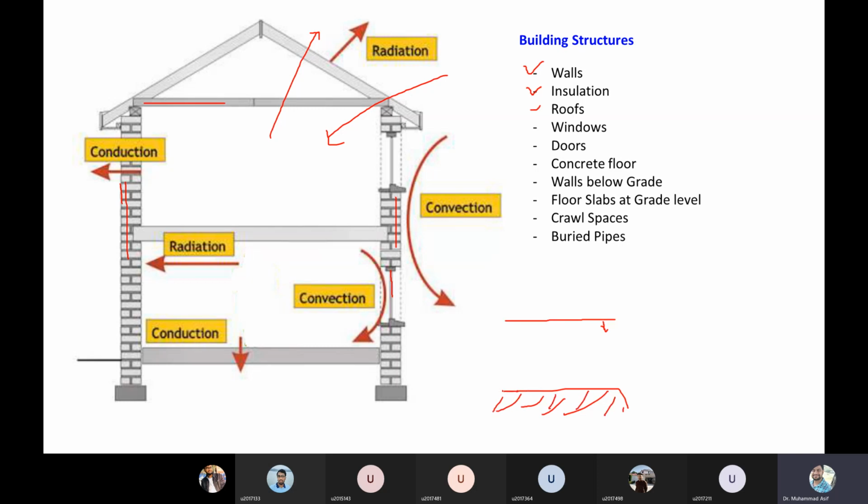And then on the soil we put concrete, right? We normally call it RCC, reinforced concrete. And then we put the grade, that's a layer of the grade. And then there is an unfinished concrete, and then we have the final flooring. In some cases they also mount some tiling as well. So when I say the floor may have many layers, it depends on the types of the construction.